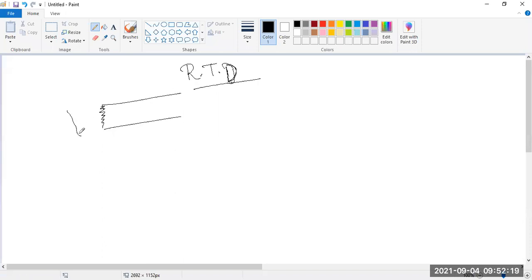If there is a temperature rise, then the value of this resistance will vary. If temperature varies, then resistance also varies. So there is a proportionality relation. So if we can measure the resistance, then by virtue of this proportionality, we can also measure the temperature. This is the fundamental logic of the RTD. Now, RTD is generally made of platinum wire, or it may be made of iron or copper for the higher range, but the common RTD is PT100.